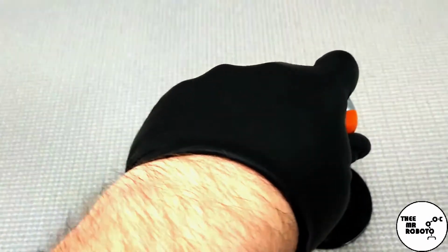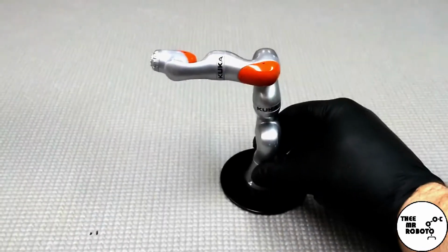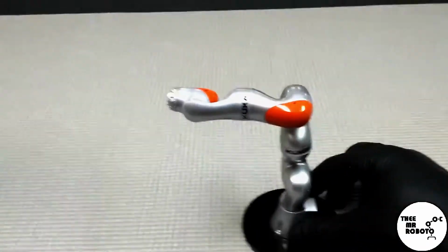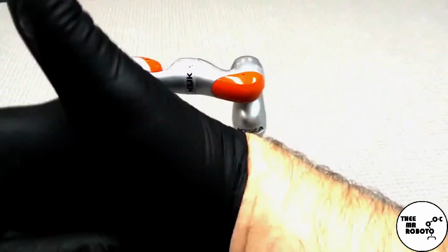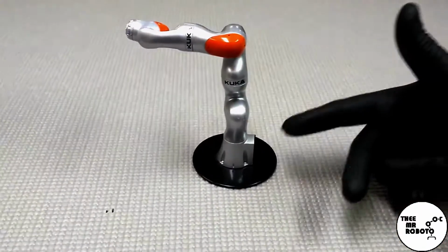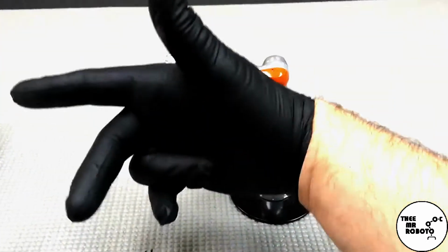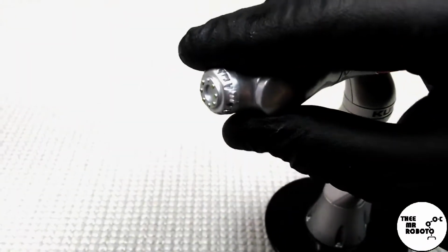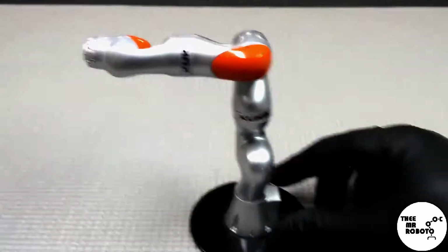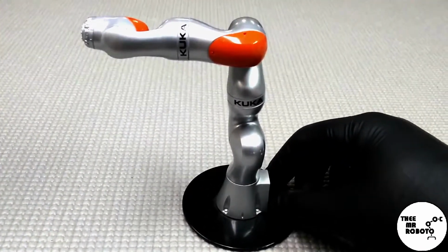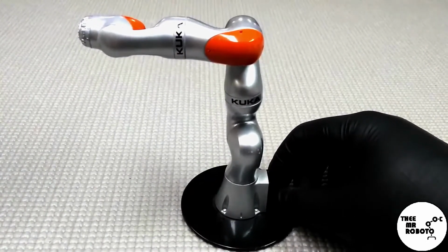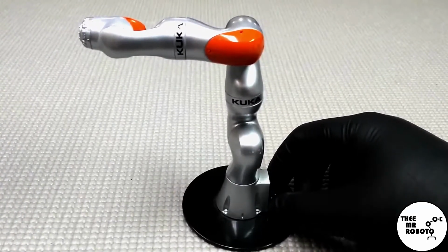Most robots' home positions are somewhere similar to this, where this part of the arm is vertical, this part is horizontal. The XYZ coordinate system at the base, okay, is connected to the XYZ coordinate system on the end of the mounting flange. Okay, so these two coordinate systems are always being compared by the robot controller.